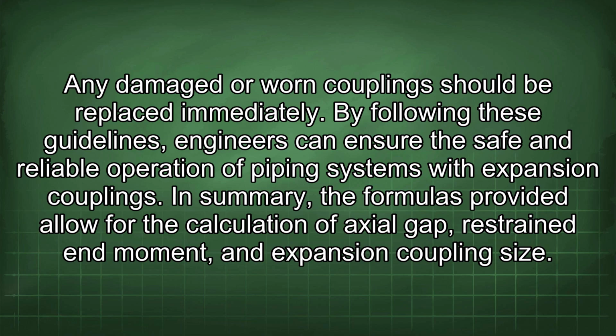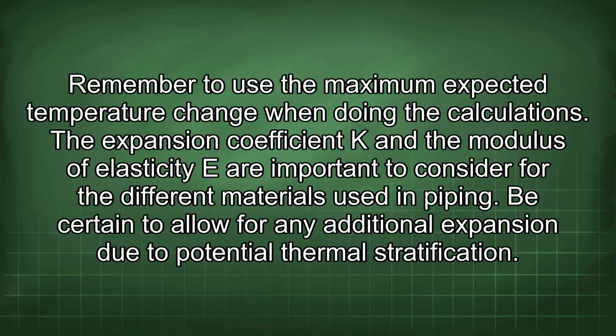In summary, the formulas provided allow for the calculation of axial gap, restrained end moment, and expansion coupling size. Remember to use the maximum expected temperature change when doing the calculations. The expansion coefficient K and the modulus of elasticity E are important to consider for the different materials used in